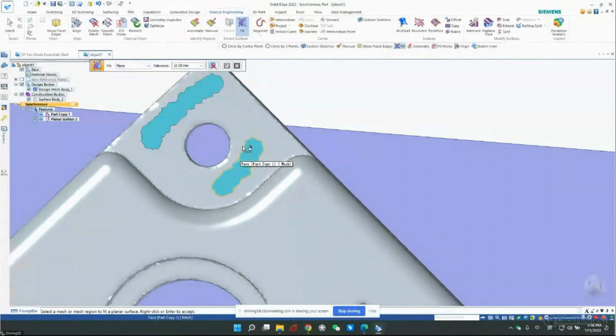And let's say some of the time you only need exactly a good location or a good feature for the hole, for fitting reasons, or if you want to put some things together, you only need the hole to be perfectly rounded, while the other areas you can let remain as the scan data shape, since you don't need much information from the surface. So you can edit only the hole area like this.